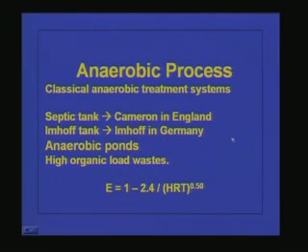So if you talk about the efficiency of this anaerobic pond, if you give sufficiently long detention time, say 5 to 10 days, then you will be getting an efficiency of 50 to 70%, or we can find out the efficiency using this empirical formula: 1 minus 2.5 by HRT raised to 0.50. Here HRT is the hydraulic retention time in days. This is the expression derived from many field experiences; they studied many field anaerobic ponds, evaluated the performance, and from that performance they reached this empirical equation.